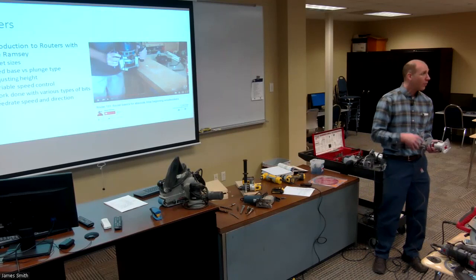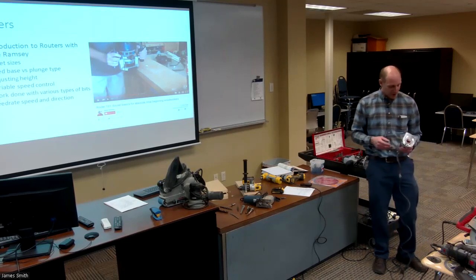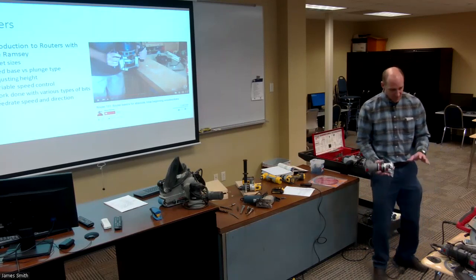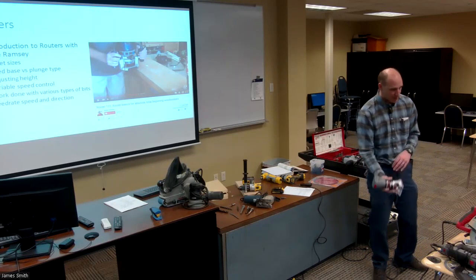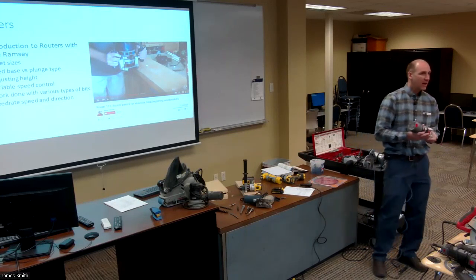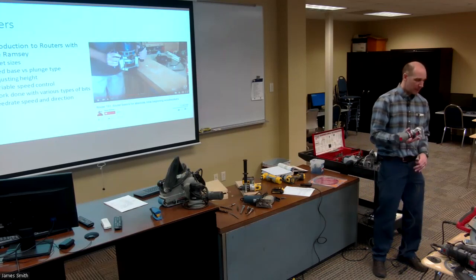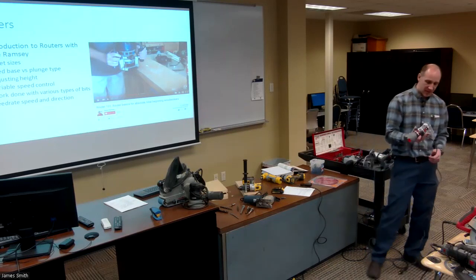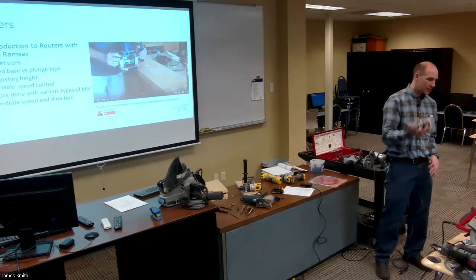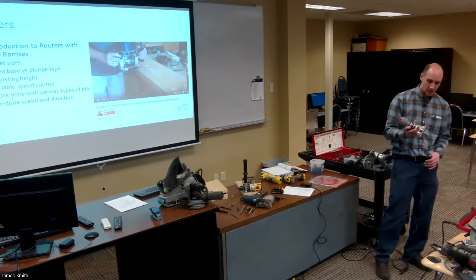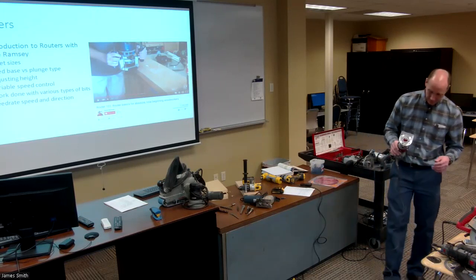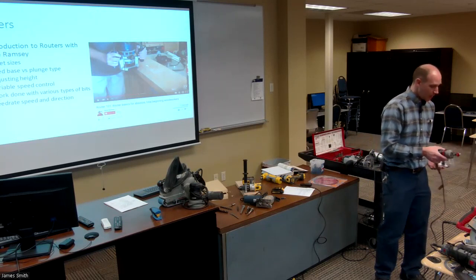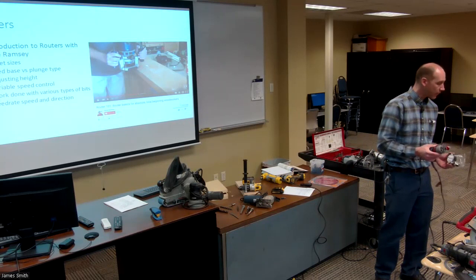But what happened is people found out that, gosh, these are really nice machines. They're lightweight. I can actually take this to my cabinet that's already been assembled and run it because the base is so small. It's very easy to manipulate. It's just a delight for doing light duty roundover applications. This is a fantastic machine, and so it's been used more and more as a router. So now they call them mini routers. This is by far my favorite. But again, these are used for doing light duty routing. Okay.